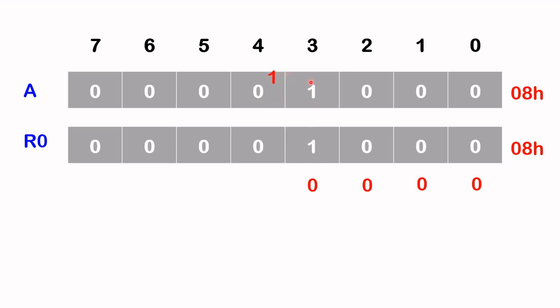Now the moment when there is a carry from bit 3 to bit 4, as is in this case, the AC flag will be set to a 1. The moment when there's a carry from bit 3 to bit 4, as is happening here, the AC flag will be set to a 1.